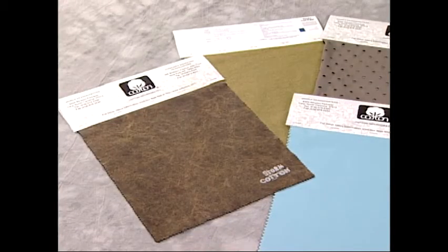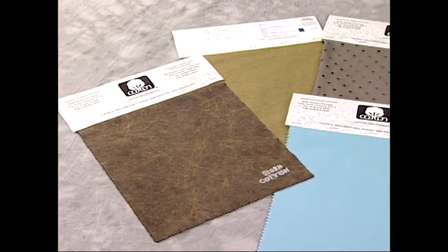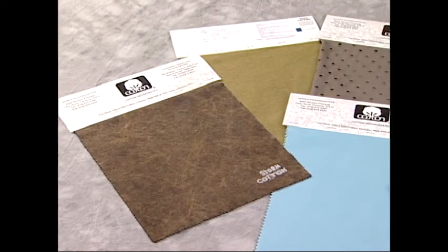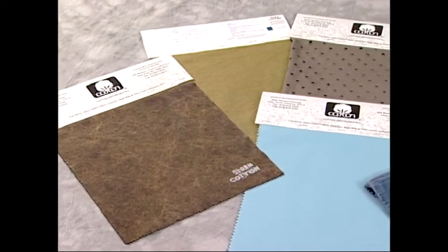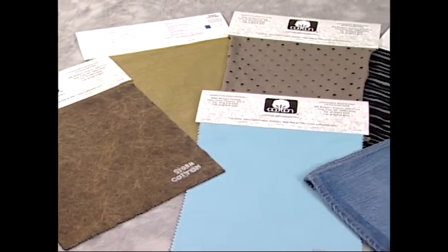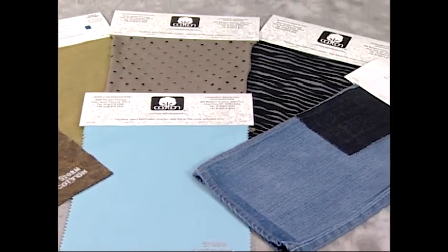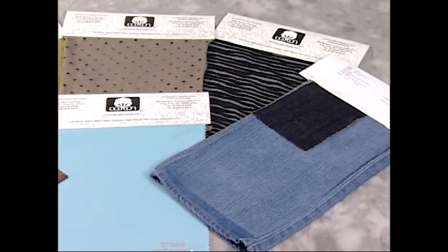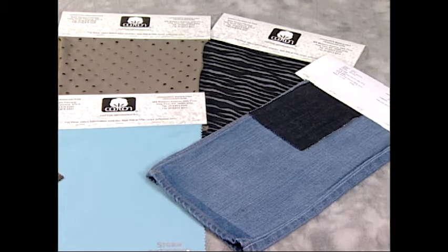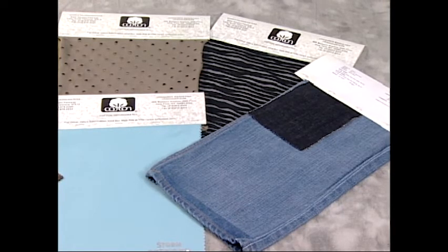Other very important considerations are the size of the specimen presented to the tester, the surface texture, and specimen presentation. The specimen must be large enough to fully cover the viewing port and to allow for folding or multi-layering. Napping, sueding, shearing, and other finishing processes to create surface texture must be properly oriented for both the standard and the specimen. Specimens must be flat, smooth, clean, and other factors related to the presentation of the specimen to the tester. Of particular importance is the number of layers of the specimen used.